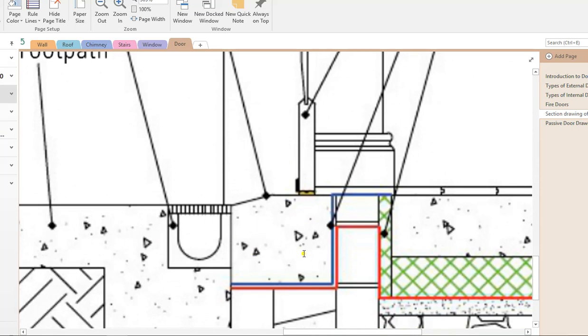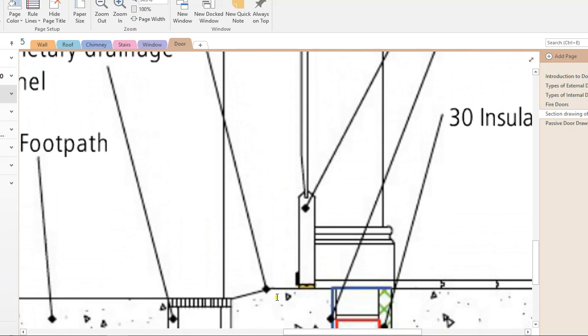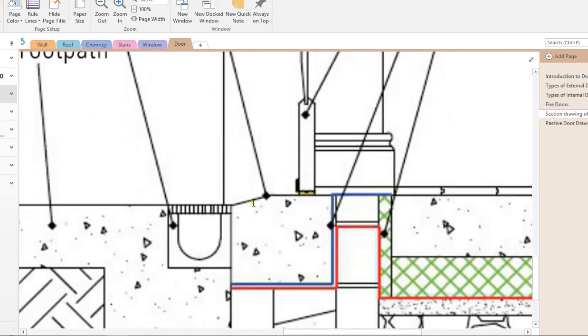So we'll have a look at the new detailing based on all of this, but what we're looking at here is this piece of concrete placed in here with a slope on it. Now the slope is a maximum of 15 degrees, and then we have a drain here to collect any rainwater. So this is a door design suitable for all users. Whether you're in a wheelchair or on crutches or able-bodied, you're able to enter this house without any difficulty.